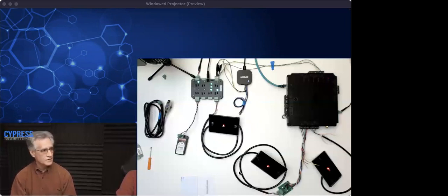Pulling new wires is not palatable at the moment. Yes, you could get away with it, I'll put it that way, running 500 feet at 9600 baud using OSDP. The problem is that, sure as anything, a year from now, someone's going to come along and say, hey, I'm going to put another device on that same pair of wires. It's been running for a year and the whole thing's just going to collapse. So yeah, you're on thin ice if you want to do that.